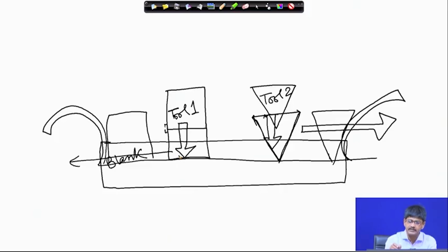So, that is why generally the tools have to have this particular shape, because it is easier for indentation. When it indents and starts moving towards one side, and if these two bodies are rigidly held, we can have removal of material. So, sharp point, wedge shape, and we will also learn that if we have sharp edges, it will also always help us to remove material. Okay. So, this is understood. We have identified what should be the desired shape of the tool, so that it can remove material.